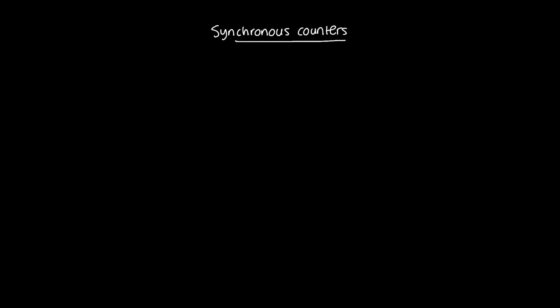Okay, so let's start building synchronous counters. Synchronous counters are counters that, unlike ripple counters, have all the flip-flops, or all the clocked elements, sharing the same clock signal. And in a synchronous counter, I will proceed in the same fashion, using the same methodology regardless of whether my counter is a natural or non-natural mod number. And this differs from a ripple counter.